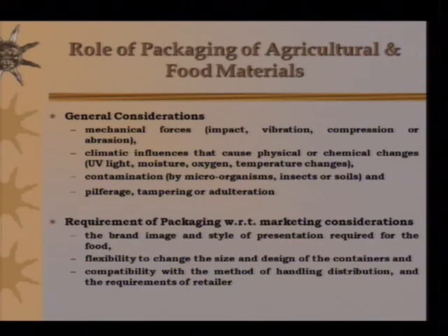We have to have two kinds of considerations. First is the general considerations for a packaging material, that it should be able to absorb mechanical forces, like for example impact, vibration, compression or abrasion. It should be able to take care of climatic influences that cause physical or chemical changes like UV light, moisture, oxygen, temperature changes, contamination by microorganisms, insects or solids, and pilferage, tampering or adulteration. A package should be pilfer proof, so that nobody can take out anything.